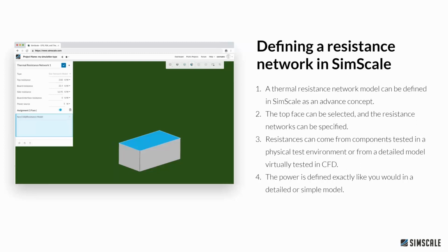So if we have a top area of X amount, then you need to have the cross-section of the top face approximately the same as your detailed model. Same with the side face and the bottom face, although typically one cuboid is just sufficient. You wouldn't want this to be a complicated shape. So the geometry we need to upload to SimScale has got to be a PCB with all of these simplified components on its surface in contact with the board.